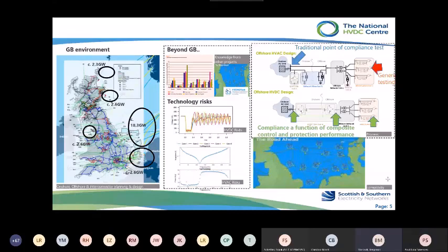If we move into the HVDC environment, then what we actually have is a control system which is communicating data associated with the onshore AC disturbance, either via the control behavior of the HVDC or via signaling, which encourages a composite response of the HVDC and the wind. Or you get a sympathetic response from the wind to the HVDC's behavior. It's entirely a function of the overall control philosophy and control approach as to what you see onshore and how the performance relates to the individual devices. There's a divvying up of responsibility going on.